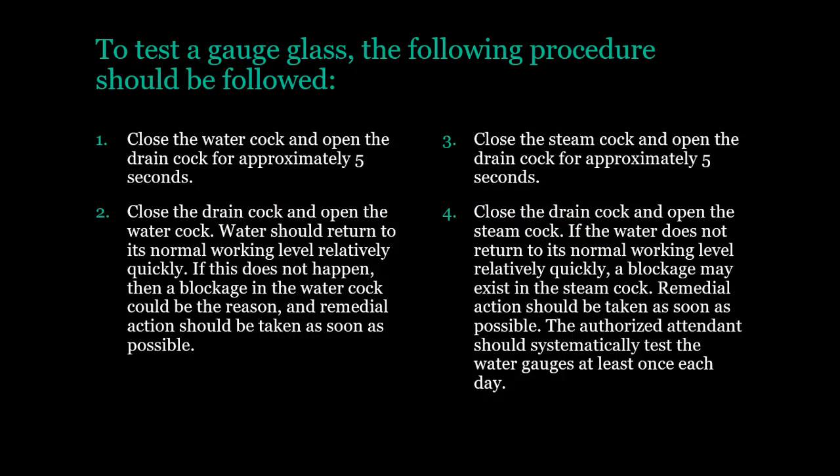To test a gauge glass, the following procedure should be followed. Close the water cock and open the drain cock for approximately 5 seconds. Close the drain cock and open the water cock. Water should return to its normal working level relatively quickly. If this does not happen, then a blockage in the water cock could be the reason, and remedial action should be taken as soon as possible.